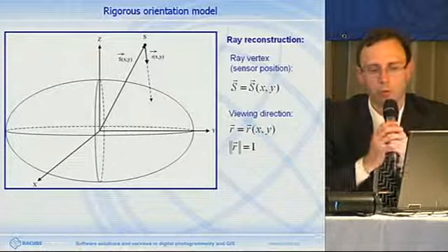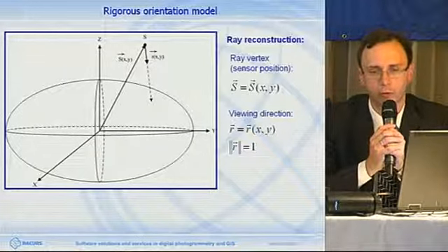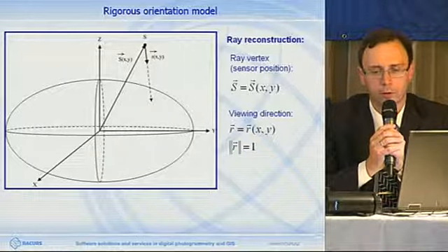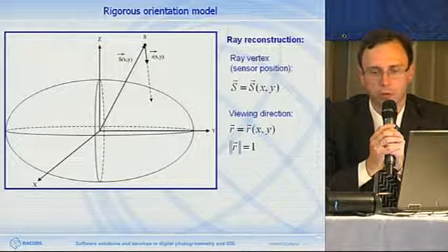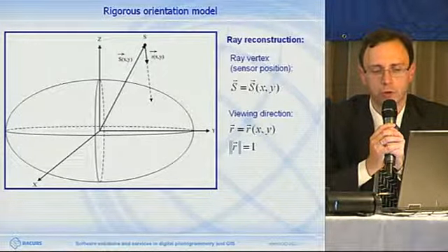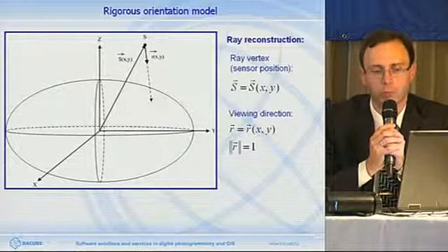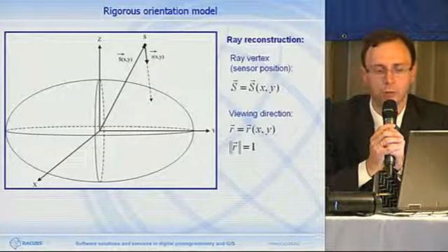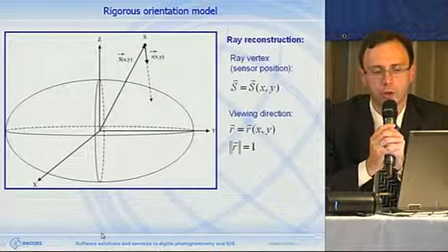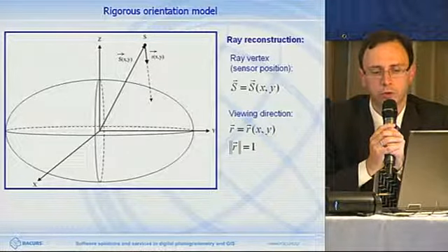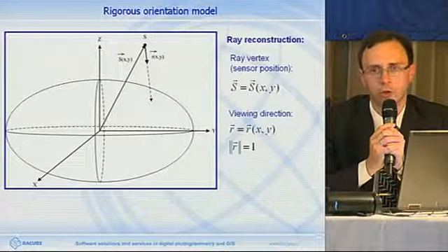And first of all, it is much easier to work with RPC, and secondly, most of the projects which are implemented on satellite imagery are orthorectification, and orthorealignment on the altitude or elevation matrices, which can be done with RPC by applying a direct formula by using Earth coordinates, and we can project them on the image coordinates, which is more efficient. And also RPC is